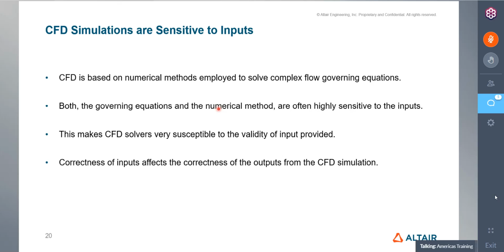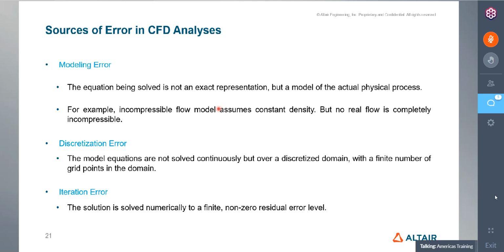But there could also be different types of errors that either we commit or an error that happens within the solution. So there's different things that can cause problems within our model, and there's just a few things that we would want to look out for. For example, we have modeling errors where, let's say we bring in a model, but we don't quite specify the boundary conditions correctly.